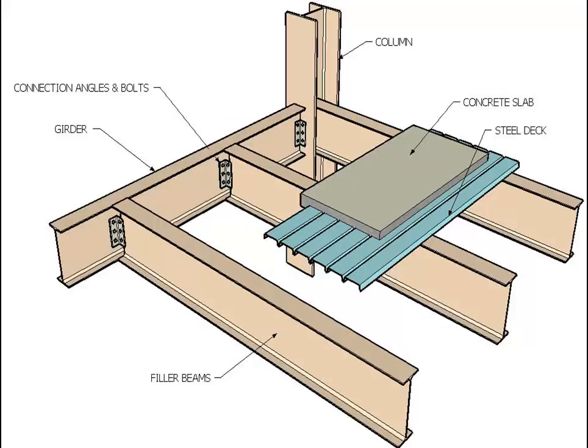This schematic shows a floor layout in a typical steel frame structure, and it's handy because it's gone through the process of labeling some of these elements. And you've seen diagrams like this in lab. Here the exterior element in flexure is being labeled a girder, and one of the interior flexural members is being labeled a fill beam or a filler beam.